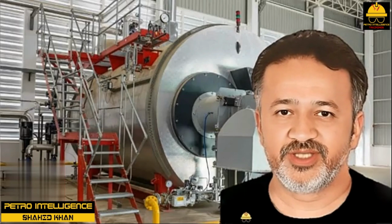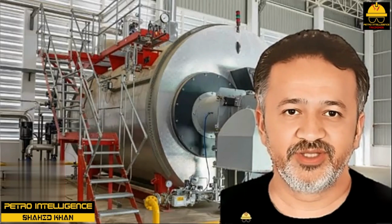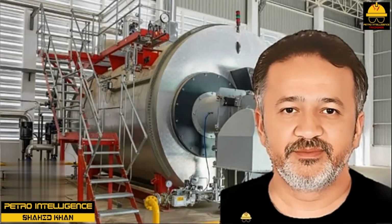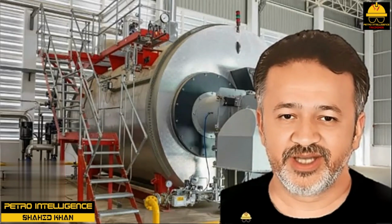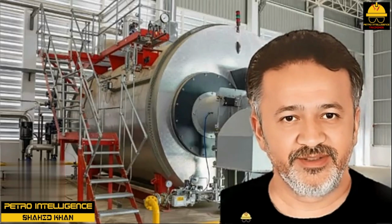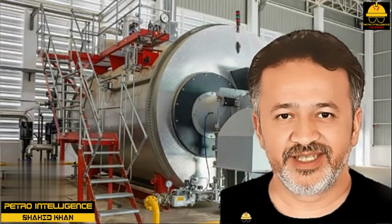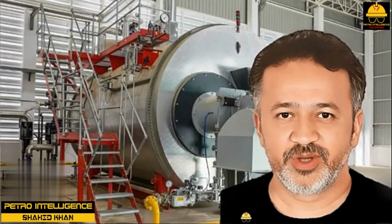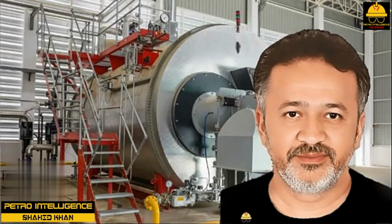The principal reasons why steam condensate is lost to the sewer are: it creates steam or water hammer in the condensate collection system. Back pressure from the condensate collection lines creates control difficulties in steam reboilers or heaters. The condensate is contaminated with traces of dissolved hydrocarbons, phenols, NH3, H2S, etc.